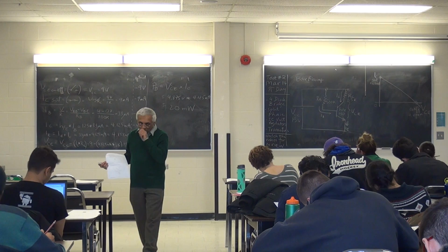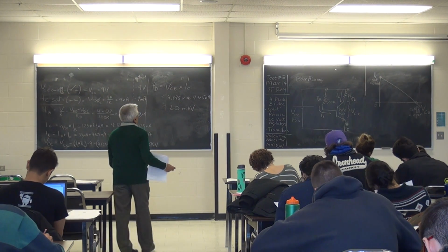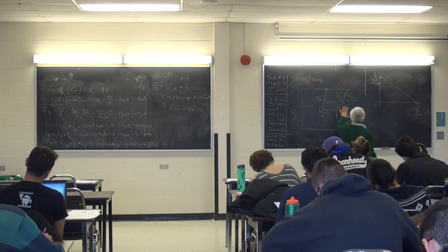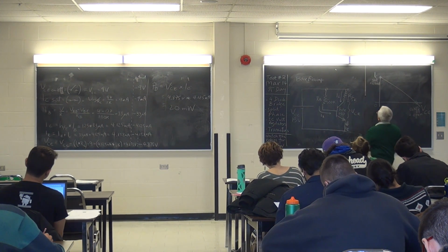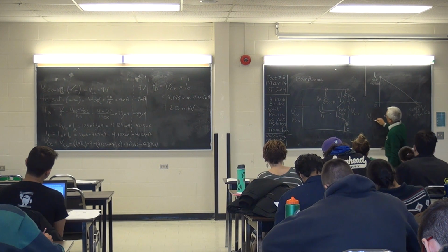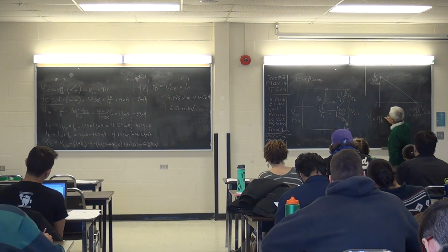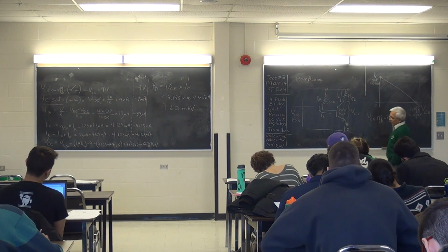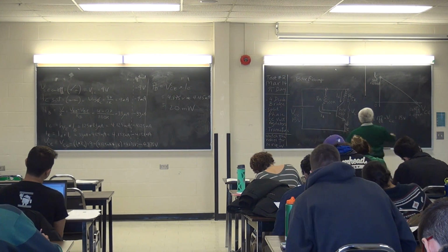Cutoff, totally open. If the transistor acts like an open switch, what is the voltage VCE from collector to emitter? How much? 15 volts. Write down 15 right here.